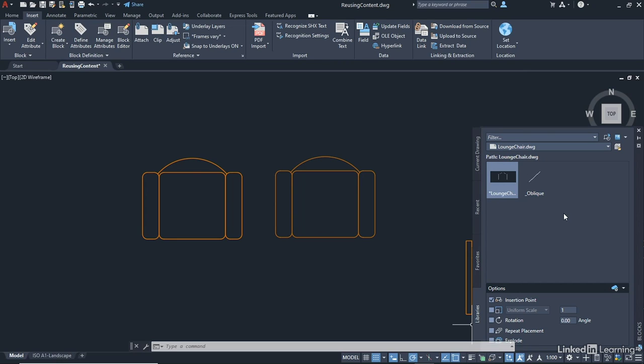It's really quick and easy, and the blocks palette in the newer versions of AutoCAD really does allow you to create blocks and redefine blocks really quickly and easily, especially if you're using that WBLOCK command as well. Remember though, this is for newer versions of AutoCAD. You might need to go back to one of the older courses in the library to see blocks used in a different way in an older version of AutoCAD as well.